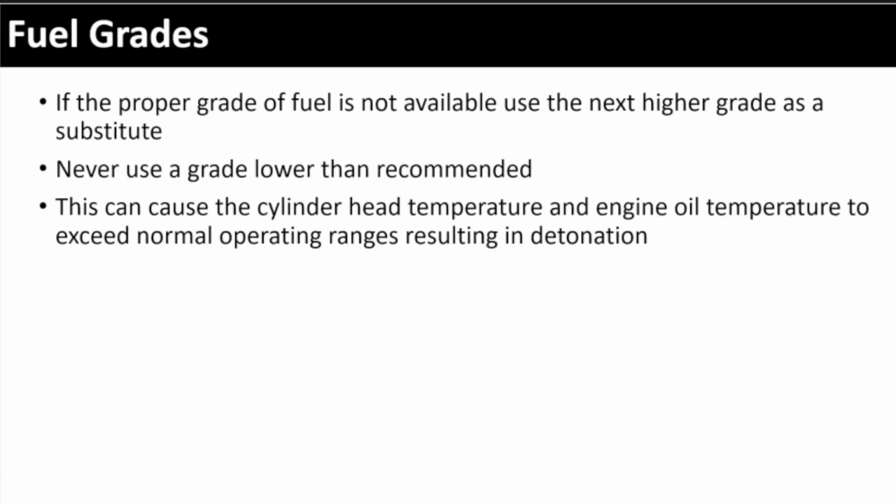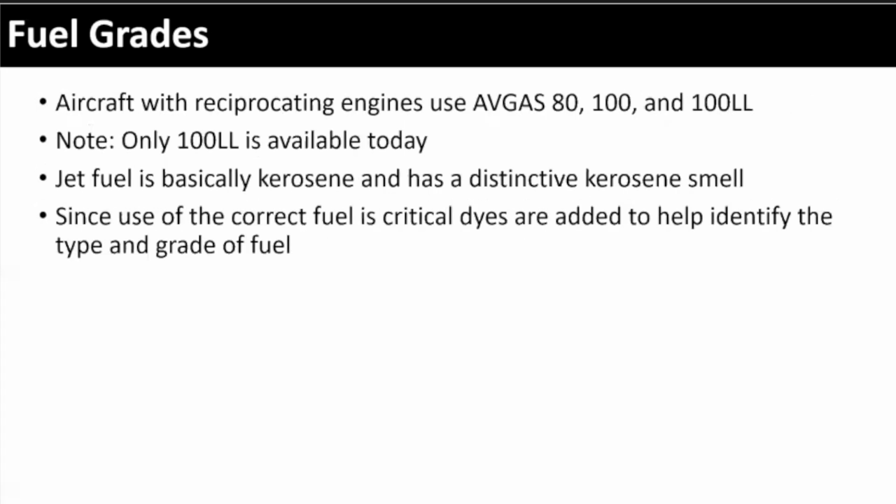If the proper grade isn't available, use the next higher grade as a substitute, right? Don't downgrade. If you downgrade, then you risk your aircraft burning too hot for that lower level fuel, right? So it's always better to go up a level.